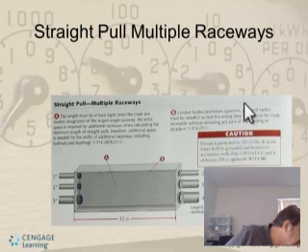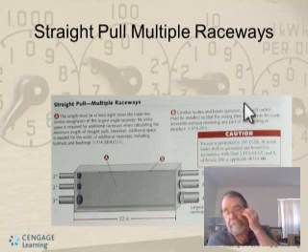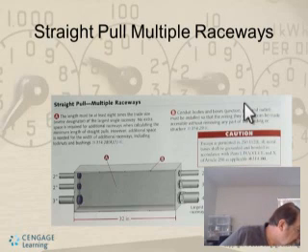There's a caution here, except as permitted in 250.112 section I, all metal boxes shall be grounded and bonded in accordance with parts 1, 4, 5, 6, 7, and 10 of Article 250. And so again, we make sure everything's grounded. If there are any broken connections in here that you need to pigtail together or something like that, a lot of times this is a pull box where you're going to be pulling cable from one direction to another.